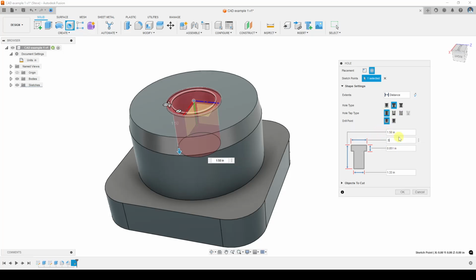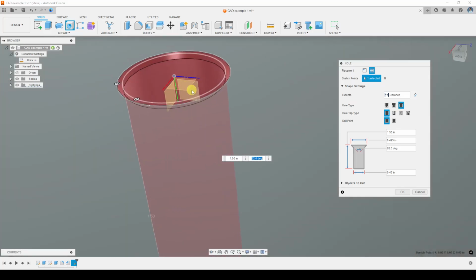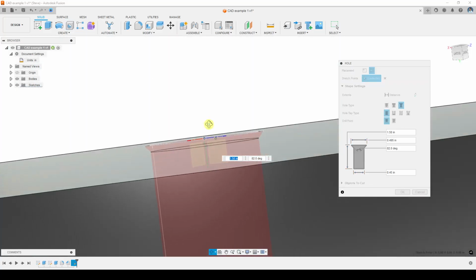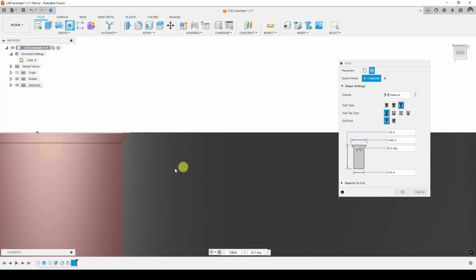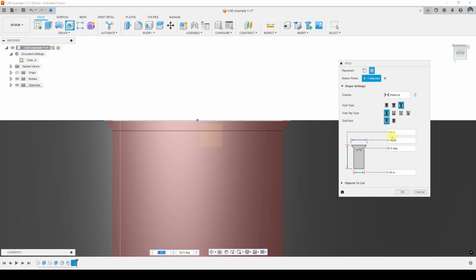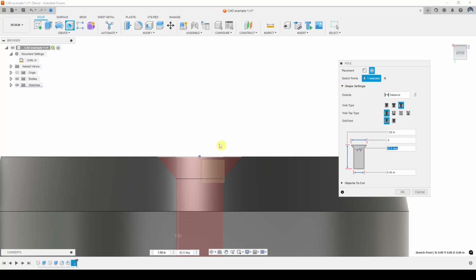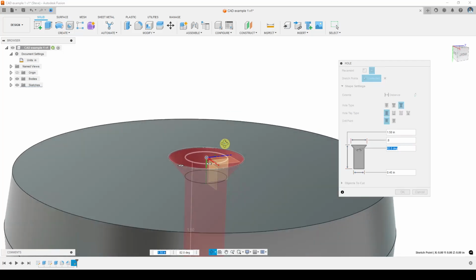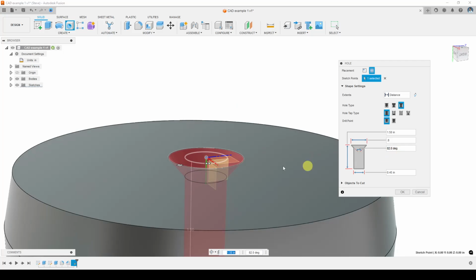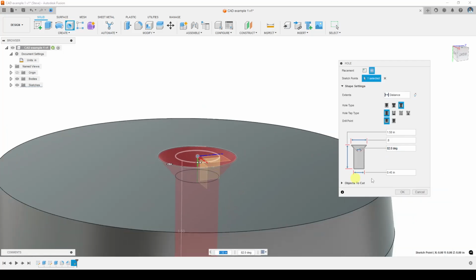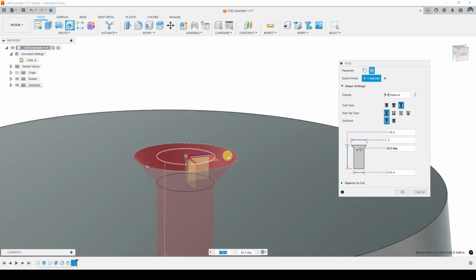Diameter, I'm going to say 0.5, half inch. And I'm going to countersink it, which means it basically has a sloped edge, which is good because sometimes the head of a screw will be sloped like that. I can specify the outer diameter here, let's say 0.8, and that makes the slope much bigger. And then you can specify the angle of it as well. 82 degrees is the head angle of a standard screw in imperial units. 90 degrees is the head angle of a standard screw in metric.